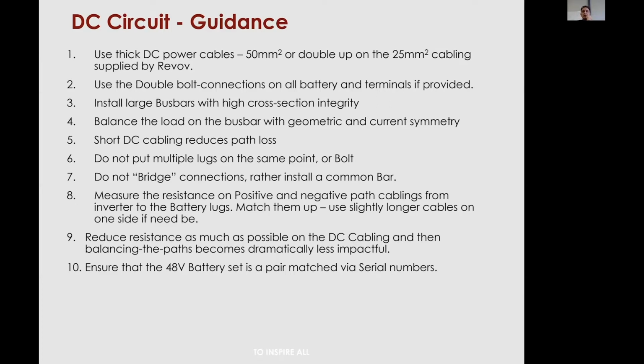You use the double bolt connections if you want to. By that I mean every terminal on the BMS and battery has 2 bolts, so they can carry a second DC cable, and install large bus bars.